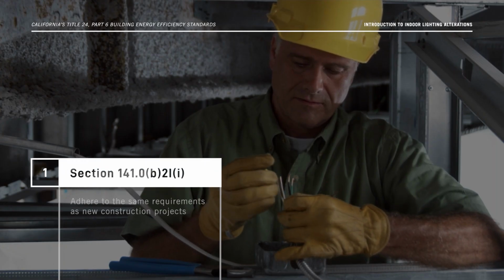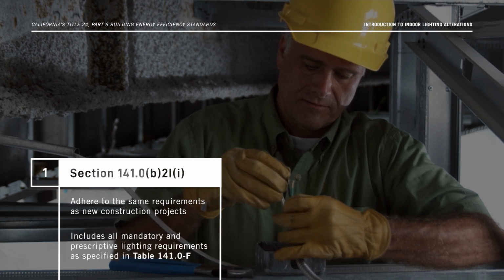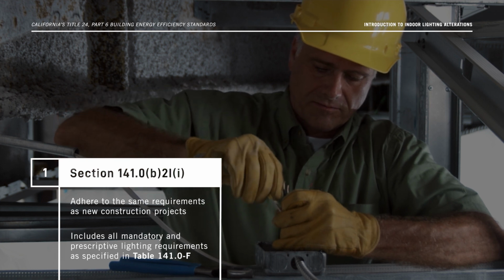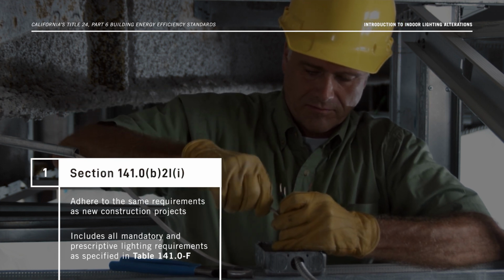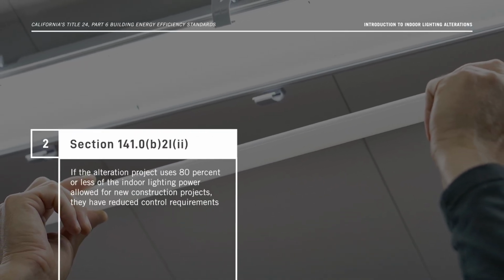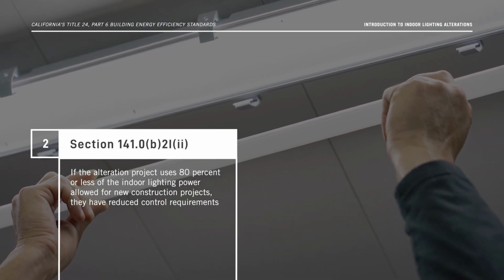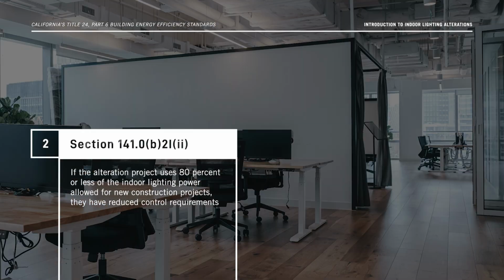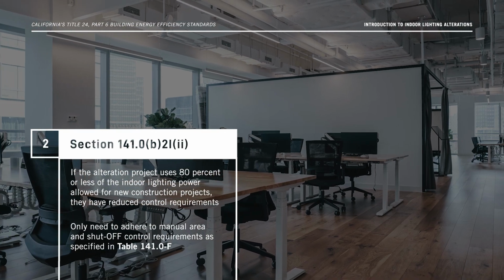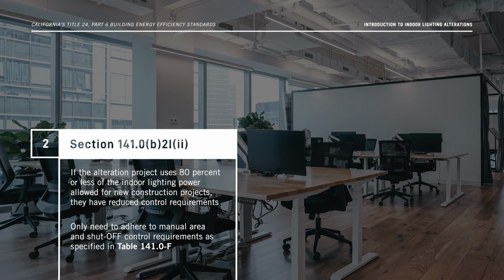Option 1. Adhere to the same requirements as new construction projects. This includes all mandatory and prescriptive lighting requirements as specified in Table 141.0-F. Option 2. If the alteration project uses 80% or less of the indoor lighting power allowed for new construction projects, they have reduced control requirements. Projects need only to adhere to requirements for manual area controls and automatic shutoff controls as specified in Table 141.0-F.